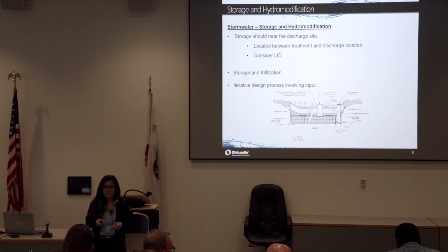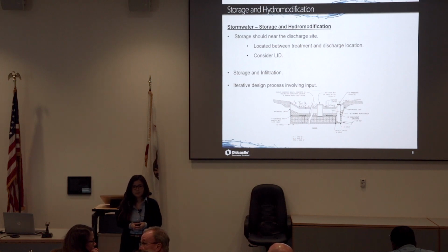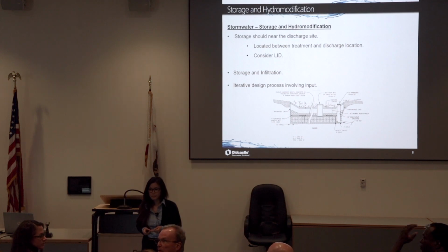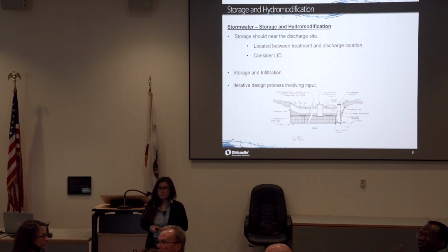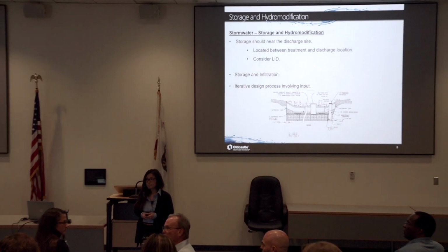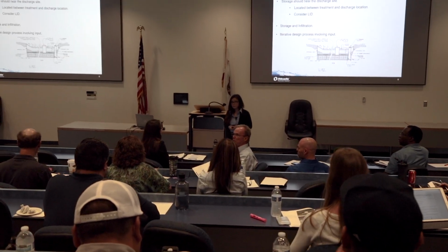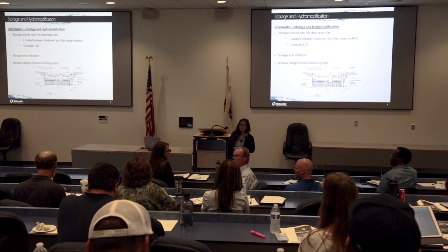Does anyone else have anything to say about that? Yeah, a lot of times we find a situation where the treatment volume and the hydromodification volume are not the same. Most of the time in these situations, the decision's already been made that we can't infiltrate, so biofiltration is acceptable.